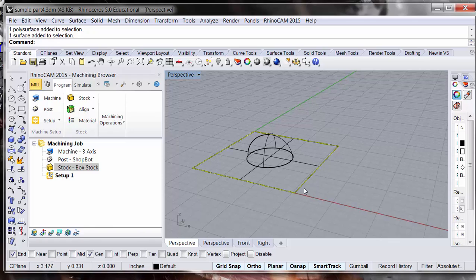Additionally, there is a curve around the outside area of this, a closed polygon, a box in this case, around my outside shape. It does not have to go all the way to the surface. I could have just done a circle here on the surface, but this is called a bounding box. This tells the tool where to stop cutting. It's a very useful feature if I've got a large area and I only need to do 3D cutting in one specific area. I can put that bounding box around there and it'll only cut to there.